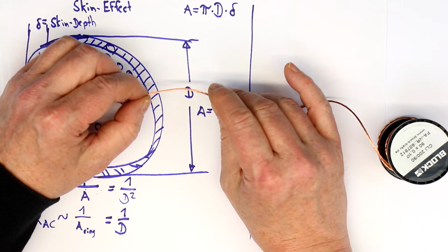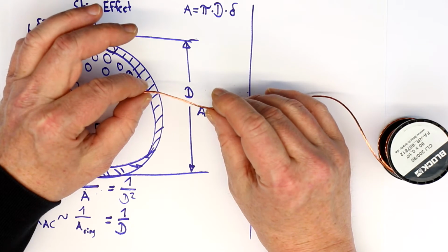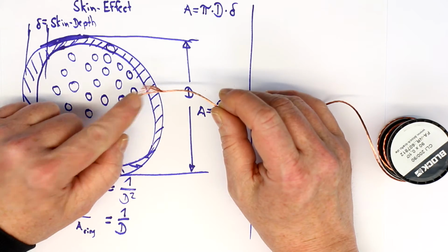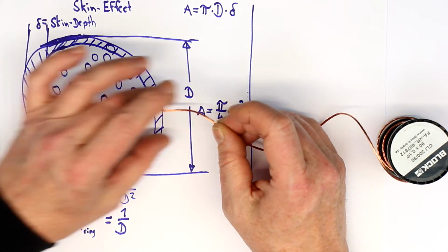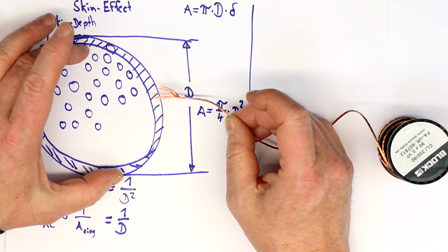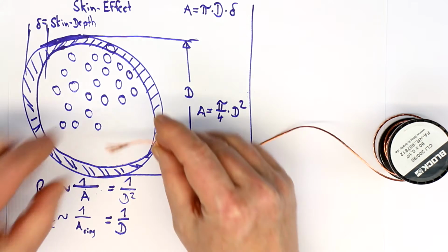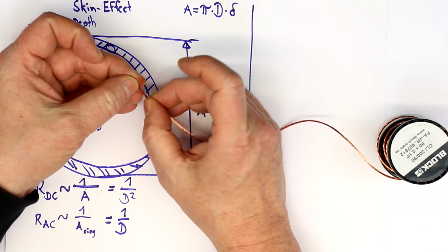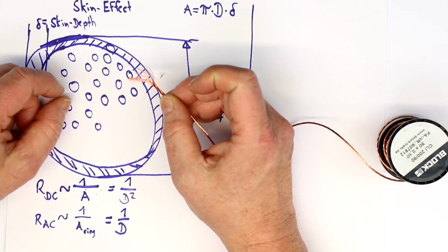So there's a whole black magic science on how to construct so-called litz-wire. So that is perhaps the more elegant way to counteract this, because we can stay at the same diameter, sufficient to give sufficiently low DC resistance, if we just split up our single wire into many isolated stranded litz wires.